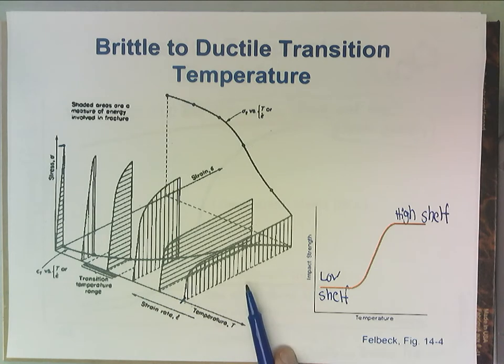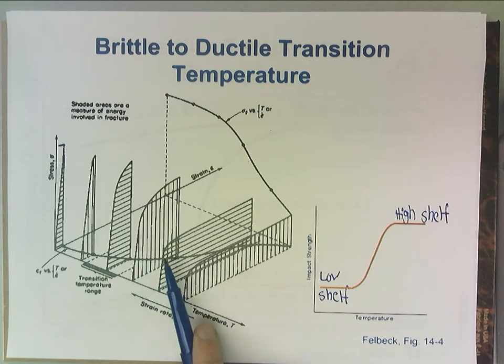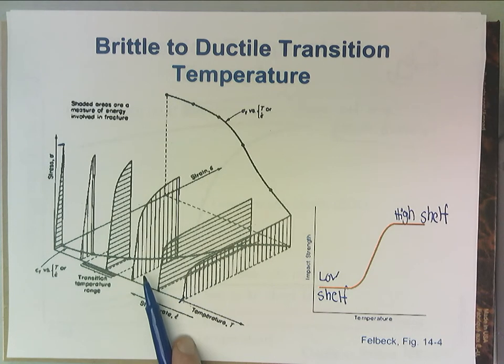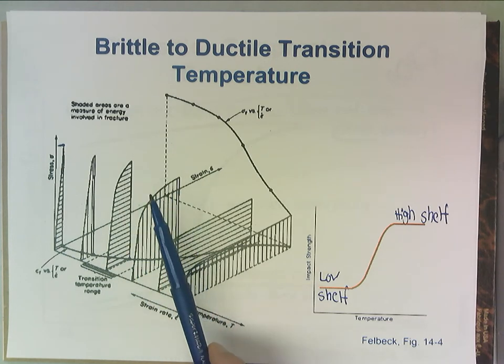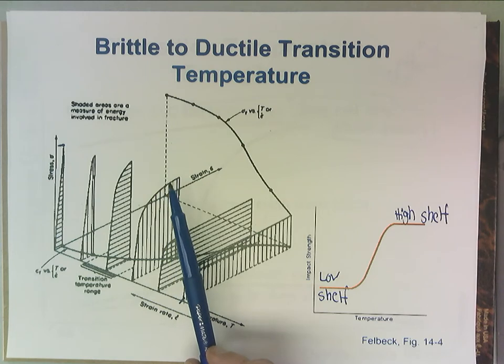Over here, this is getting more into the range, maybe something in the middle ground here. This is what we want to build a lot of automotive components out of. Why? Because it's reasonably strong, which means I can make my components smaller and save weight, save fuel efficiency. But in an impact, like an automotive collision, there's still reasonable energy under the stress strain curve.